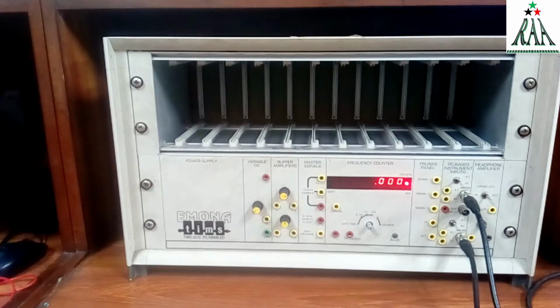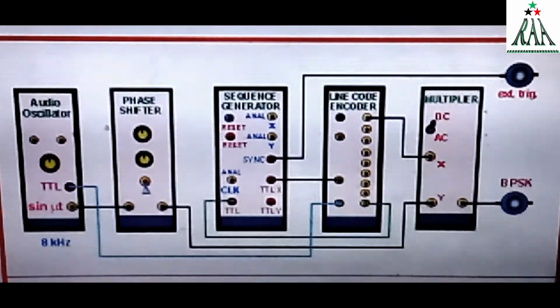To properly understand this experiment or lab, students must go through this experiment and read it entirely to become familiar with its objective and how we will perform it by using hardware and software. Before performing the hardware, we will go through the schematic diagram for performing this experiment. The shown figure is the schematic diagram for generating BPSK. So by using this diagram, we will generate BPSK.